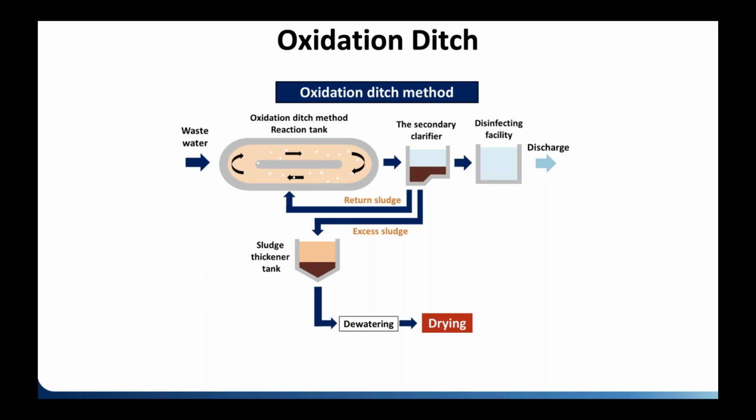And part of the advantage of this is that when you're moving the water around in a circle and it's being mixed and it's traveling, you get a lot of ambient air transfer of oxygen, and you also have mixers in there that are mixing it intermittently. So you can rely a little bit more on Mother Nature to create the aeration as opposed to having diffusers from the bottom.